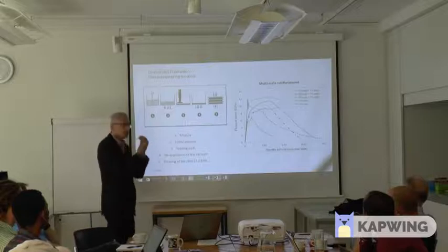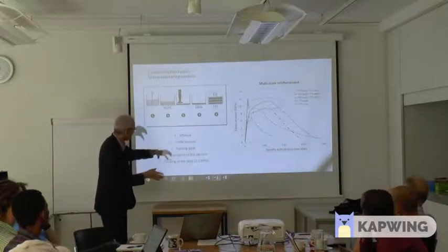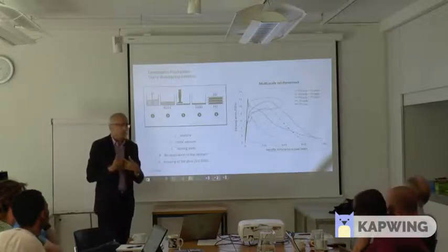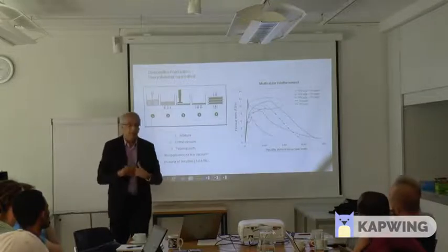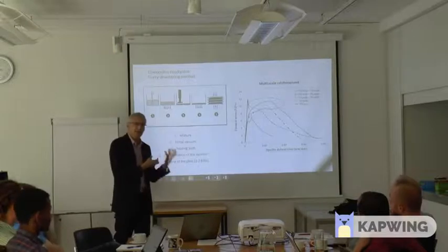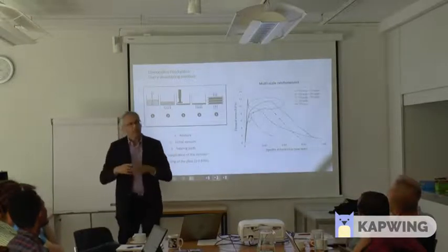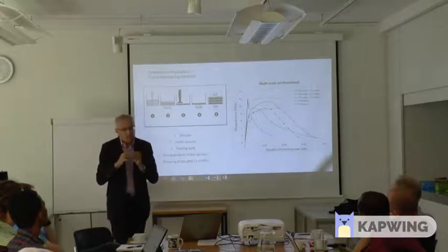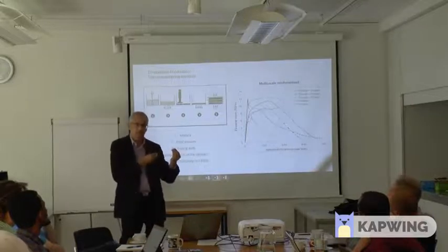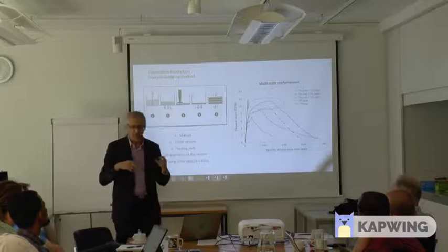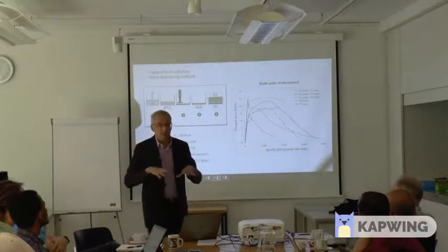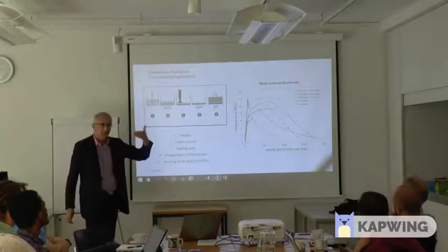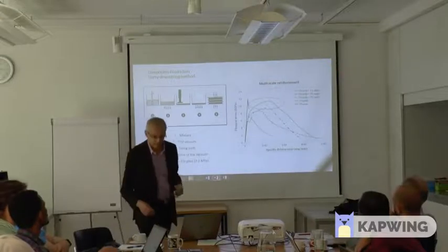So we had to modify a little bit also the side of the matrix to get all the potential of the pulp, and also from the nanofibrillated materials. We have to modify, for example, the carbonation I told you about, which is refining the porosity and then making this porosity compatible with the nano-reinforcement. Otherwise, the nano-reinforcement will be lost inside of that big amount of pores. Just to have an idea, these products have up to 35% of porosity inside.